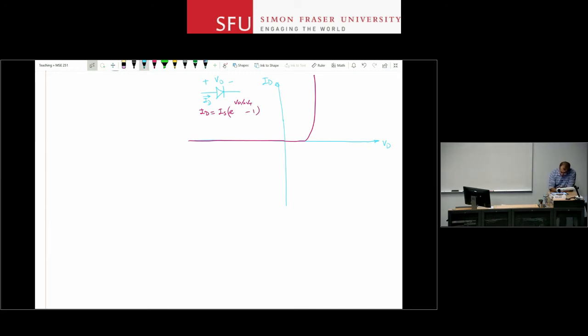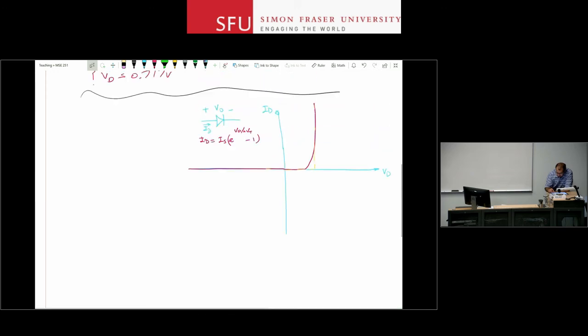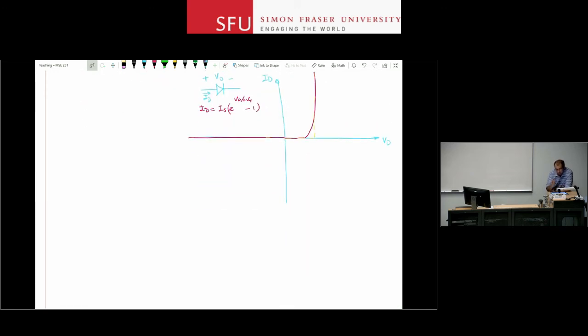Now, as we said before, we noticed that the IV characteristic curve for a PN junction is similar to an ideal diode characteristic curve that is shifted to the right. If I look at an ideal diode characteristic curve, the orange curve here, it looks like that. A PN junction is resembling that, with the exception of a little bit of curvature at the bottom here, but it's shifted to the right a bit. By how much? By this value, VD on. So it looks like that, once you turn on the diode, the voltage doesn't change by much from that point onwards. We call that VD on.